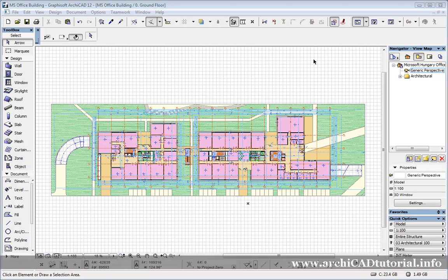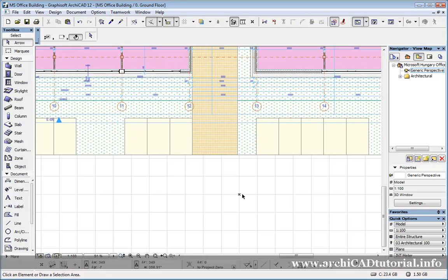The project origin is a location which always stays the same for the entire life of the project. This, in our project here, is the project origin. Basically, everything within the internal data structure of the file is measured from this point. So every wall, every element is measured from this point. And so this is basically a global reference point for the whole project.